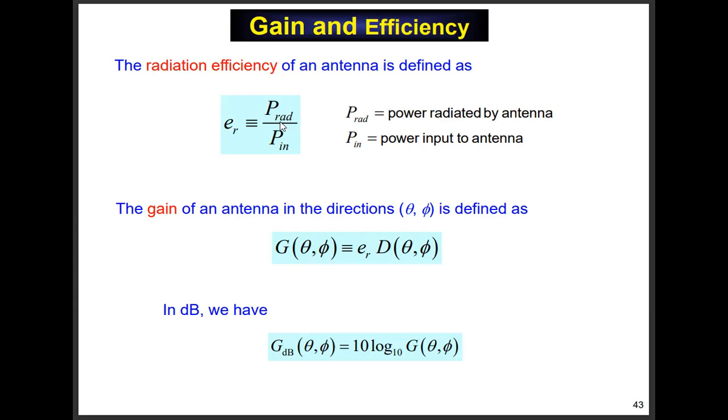Okay. Now, why is an antenna not 100% efficient? Well, the antenna is made out of real copper, aluminum, and depending on the type of antenna, maybe dielectric loss. A wire antenna would not have that, but a microstrip antenna does, because it's made on a dielectric, a substrate board, right? So a microstrip antenna not only has metal loss, but dielectric loss too, the loss tangent of the dielectric. So it's kind of worst of all.